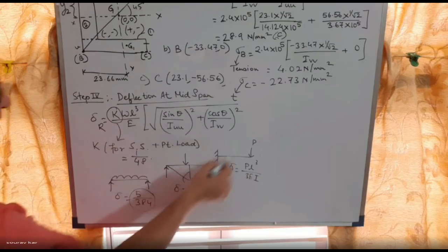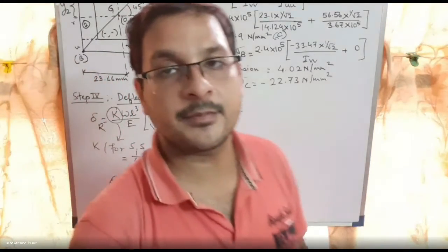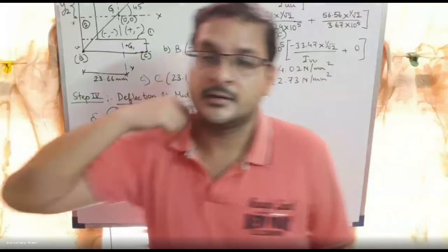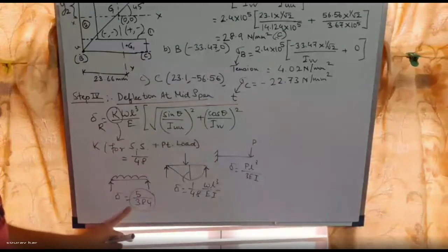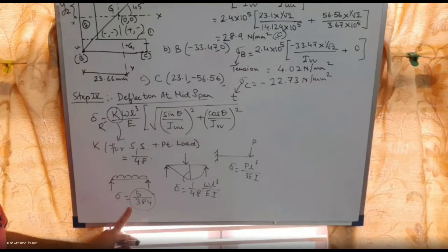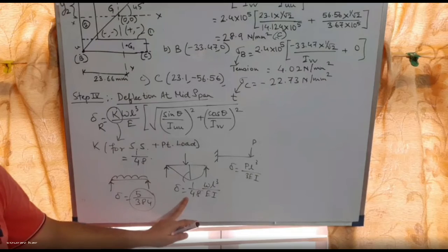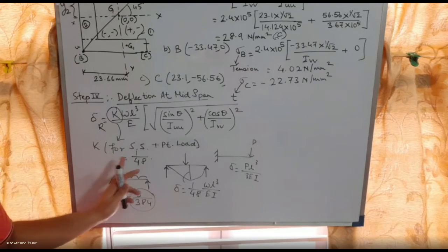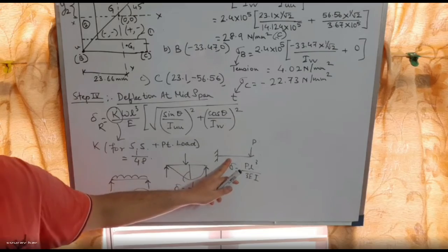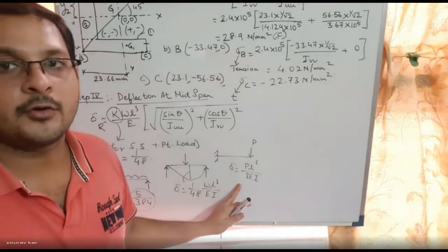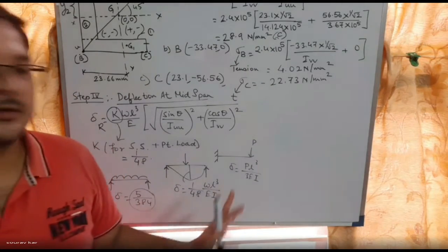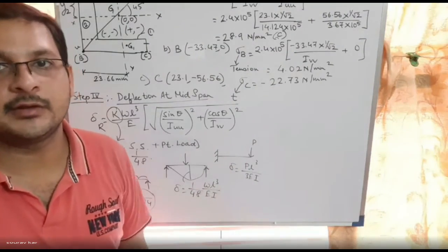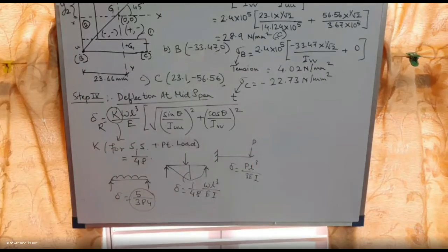So this you have to remember from the slope deflection chapter which you have learned in second year, in structure analysis 1 or strength of materials. The deflection for a simply supported beam under UDL is 5 by 384, this is the coefficient. Similarly, for point load 1 by 48, which we require here. If the beam is a cantilever under point load it will be 1 by 3. All these 4 different cases you have to remember, also cantilever with UDL, which you see from the chart.